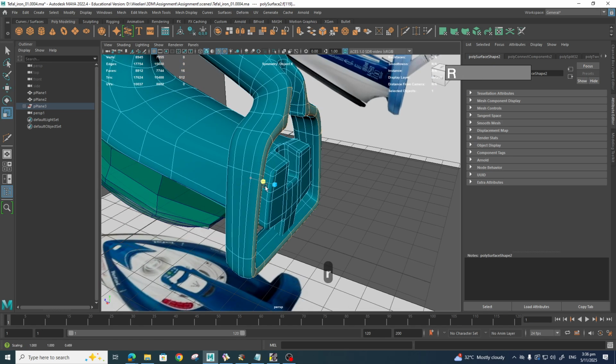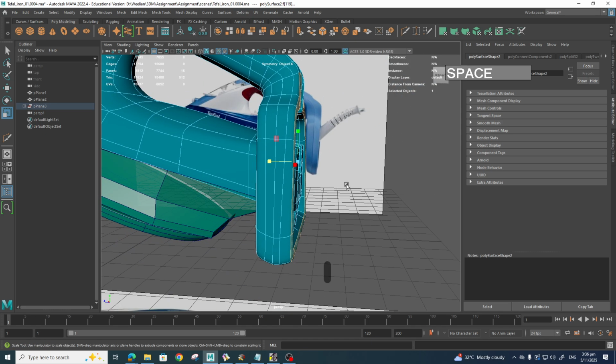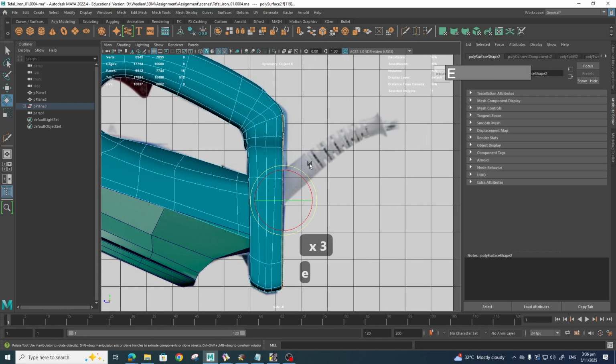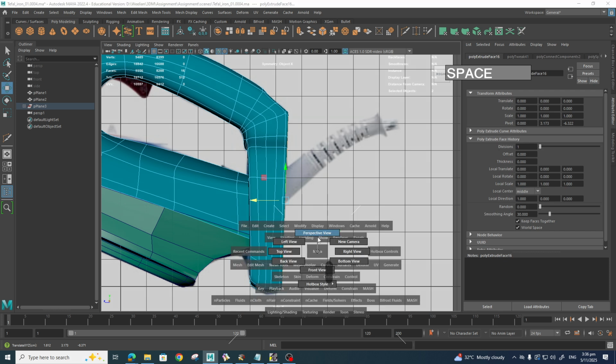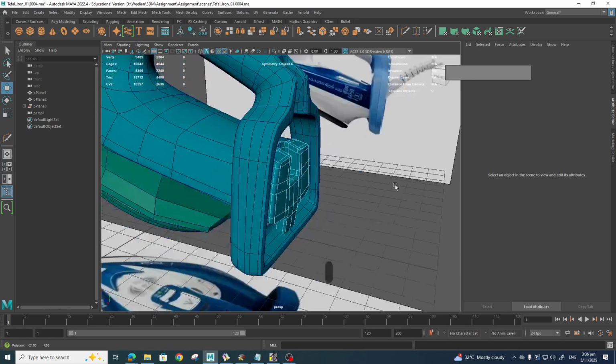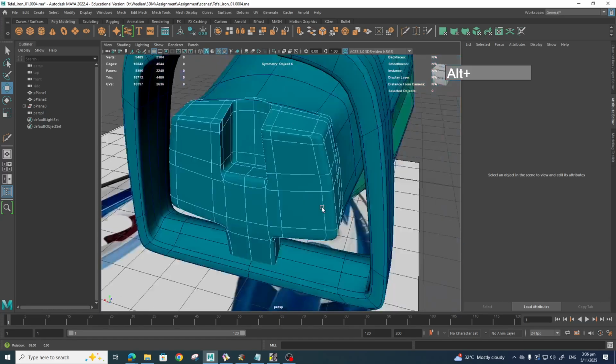I'm going to use scale to try to flatten it first. Let's go to the right view. And because the scale is being rotated, I'm going to rotate it back a little bit, and then from these faces I'm going to just extrude one section out, and then this will form a flat base, flat surface for the iron. You can see right now this one is relatively flat.